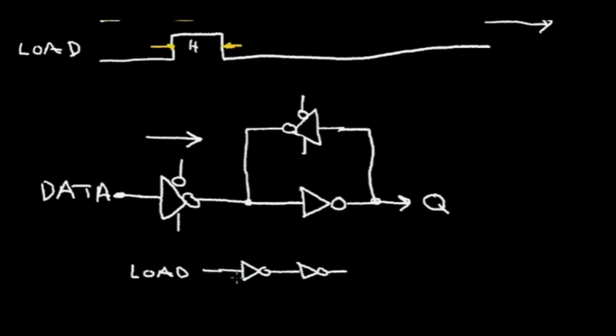Well, I'm going to label this node. I'm going to give this a name. I'm going to call it NL for not load. I'm going to call this output, I'm going to label it L. And I'm going to connect L over to the NMOS of this input tri-state driver, and I'm going to connect the NL not load signal up here, and I'm going to reverse the connections on this upper tri-state driver. This is going to be the L signal, this will be the not L signal.